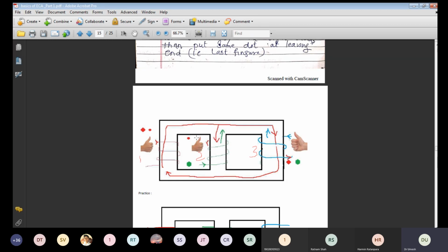The dot is not there. The direction of current is not given to you at the start. You have to put the direction, and you have to relate this winding with this winding, meaning how these two windings are mutually coupled. It may be opposite, or it may be in the adding criteria, or the subtracting criteria. Now if you want to put a dot, say this is our first winding, that is N1. We have to relate one winding with the second winding, one winding with the third winding, and the second winding with the third winding.